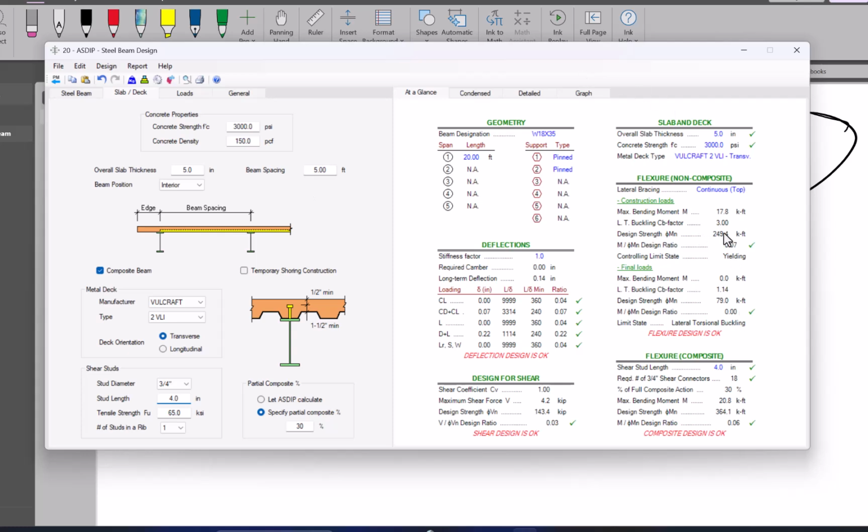You can see the strength. You can use any software you want and you'll see the same section, same forces, same span. If you use composite action, you get almost 40 to 50% increment in the strength and capacity of the beam. And if you do it the regular way with non-composite flooring systems, you probably get one third less strength, or even more, so you have to compromise. So why not choose a composite flooring system, and reduce the steel section sizes and the weight of the building. Apart from this,